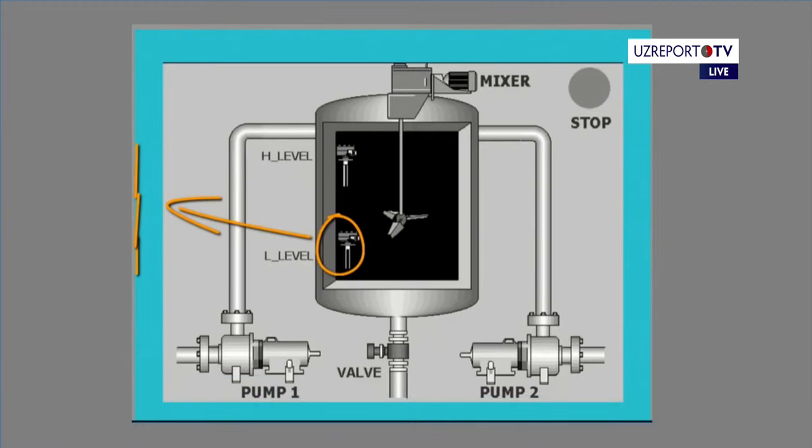Okay, first of all, the algorithm, how it will work. Let's imagine again the relay and the technology process. Here we have a low level. The low level sensor is used to connect and switch off or switch on, it's a switcher. When we detect a low level, that is, the level of liquid is low, it gives the signal to the pumps to switch off.